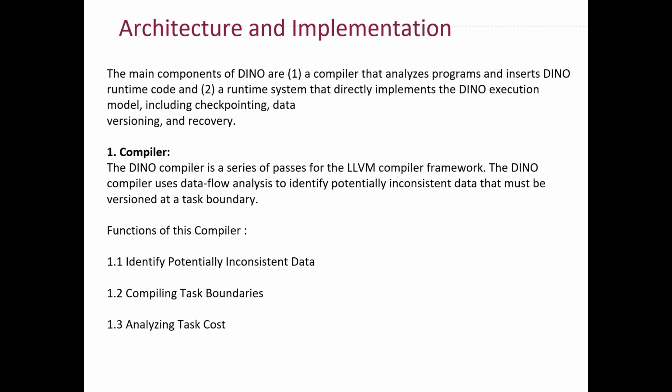I mean, this is kind of difficult to understand at first, but this just means that you kind of know what variable was written to the non-volatile memory if you traverse the control flow graph and you hit the most recent DINO task. And if you hit the most recent DINO task, then you kind of get a whole log, not a log file, that's kind of wrong, but you kind of get information as to what stuff was stored in the non-volatile memory.